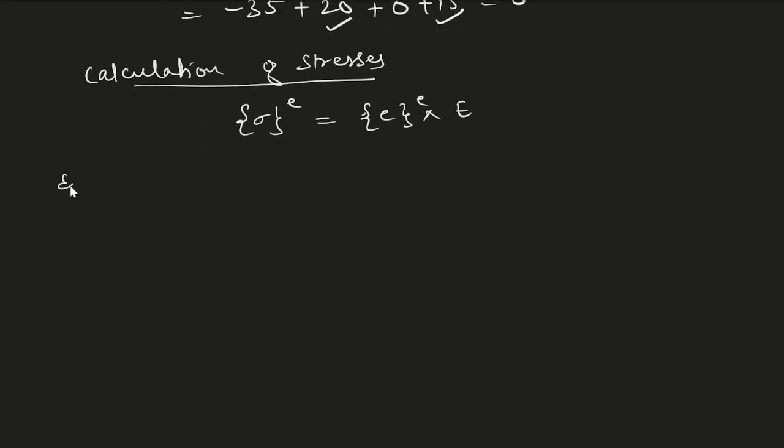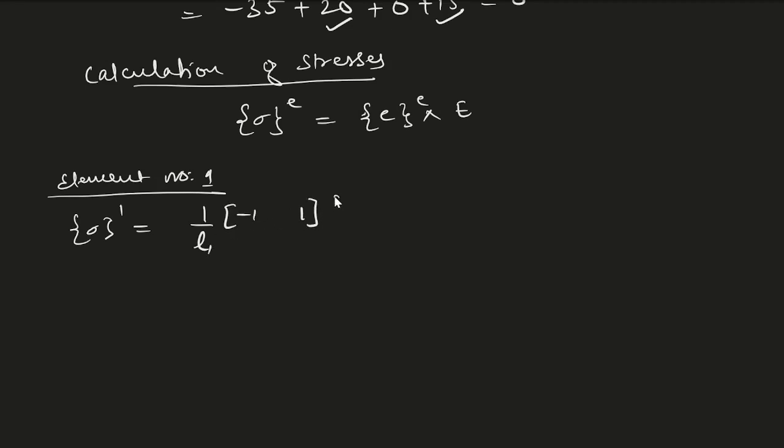So for element number 1, the stress for 1 is equal to the strain, 1 by L1 into minus 1, 1, into U1 and U2, because it is the first element, into E. E is 210 into 10 power 3, L1 is 150.